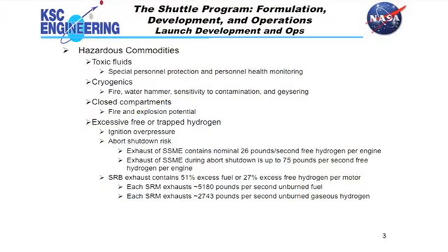Closed compartments, again, are a difficult area. They drive costs because they require you to control that area. If there's hazardous gases that can be in there, you need to monitor those, so you have to have monitor systems. You need to put inert gases in there, but if you need to go back in those areas, you've got to have a conversion system to get the inert gas out and air back in.